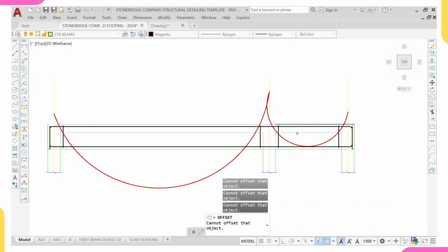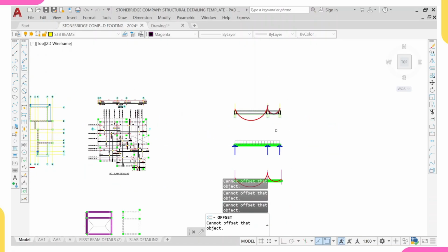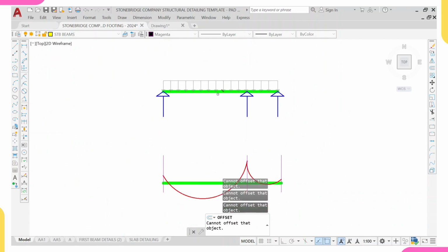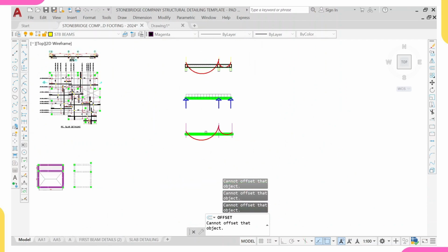That is why in slab, wherever we are having a beam, we provide top reinforcement at that zone. Because if you do not provide top reinforcement, that means you will not counter for this moment. So this is the main reason why we provide top reinforcement in slab. And for example, this is the free body diagram, and this is the bending moment diagram. I hope I've explained this.